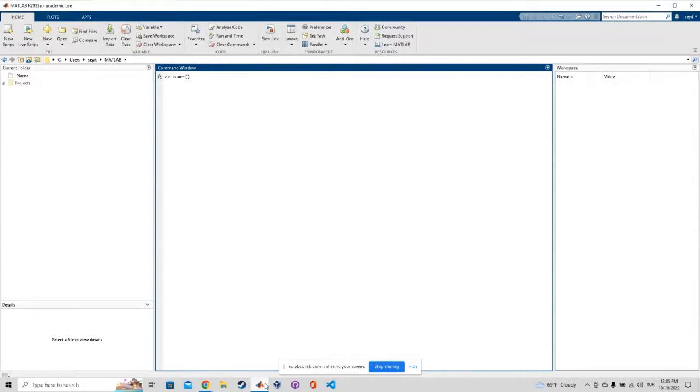Okay, let's say we have a numerator. You can define it as whatever you want. And your denominator. Define your numerator and denominator. Let's say hit enter. For the partial fraction of a system, you just write parentheses r comma p comma and again your k. Right? You just hit equals residue. If you want to take a partial fraction, you just write residue. The rest is the same, and then open parenthesis numerator comma denominator. Right?